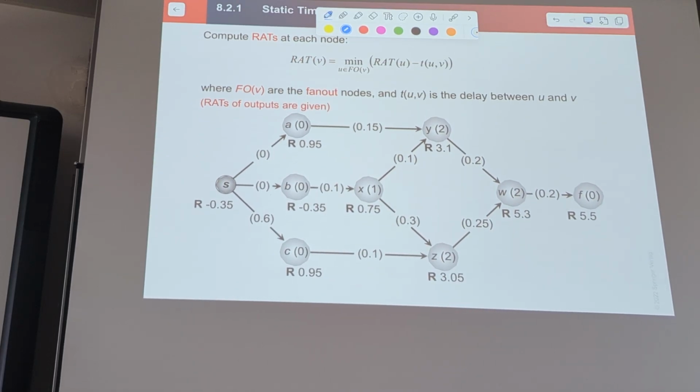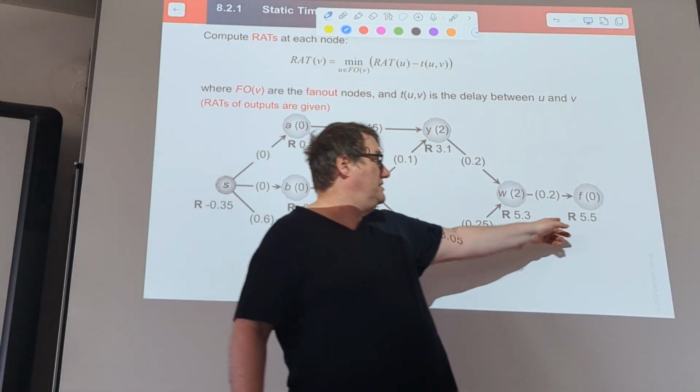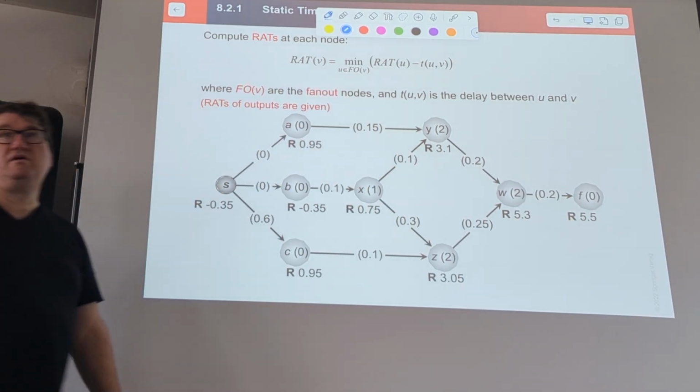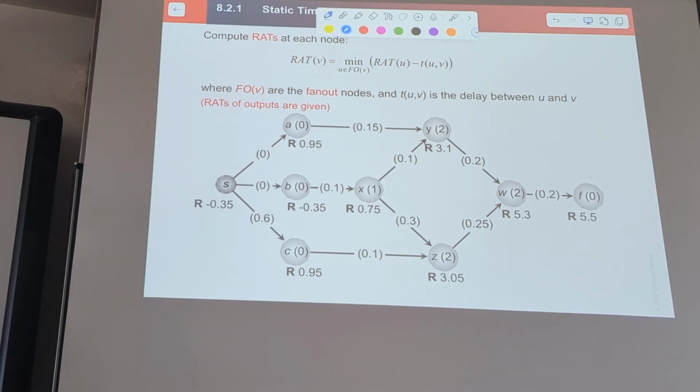The required time is working differently. I showed that in the timing analysis report from the FPGA, where they said, yeah, the requirement at the end is my clock when the receiving flip-flop is clocked, and the setup delay. That is my required time. But you can, so this one is given from your flip-flop basically.